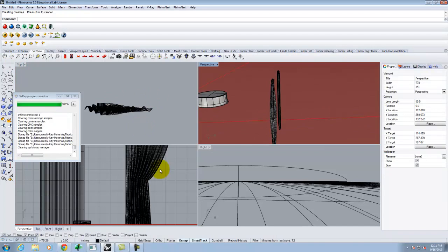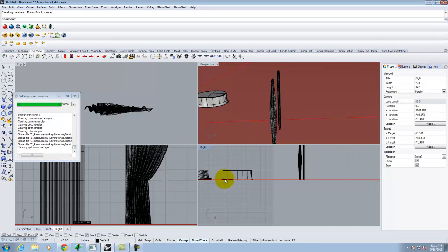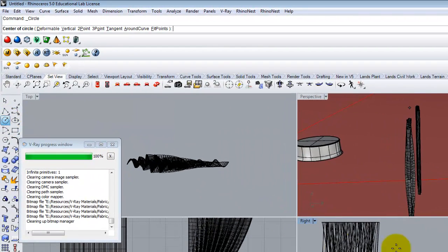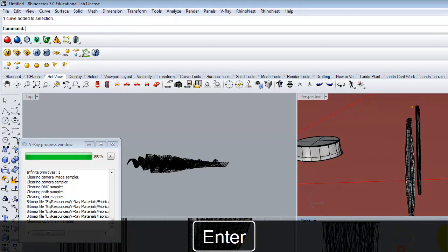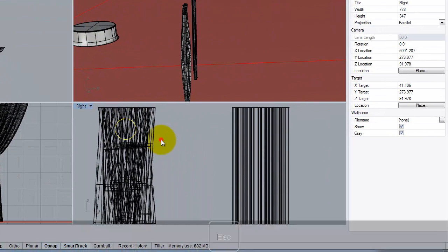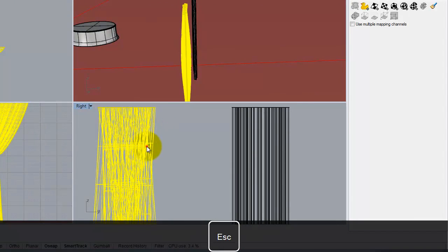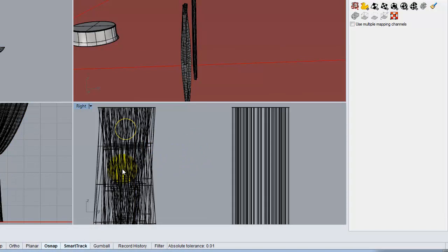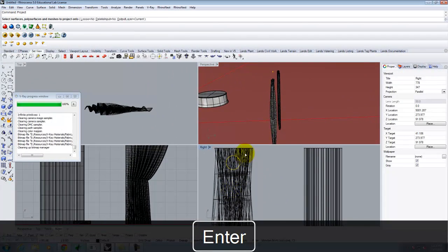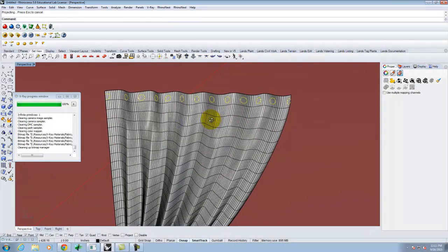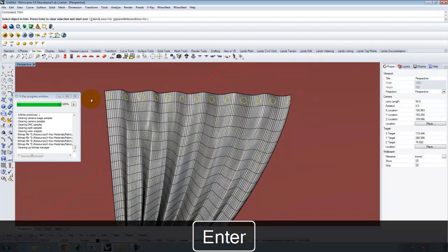Let's have fun. You guys are like, too much, stop talking, right? Okay, so let's say that I wanted a curtain rod to go through. So let's say I had a diameter of, I don't know, 1.5 inches. Something like that. Let's move this over to there. Like that. All right, let's take that curve. Project onto that surface. There's where the holes would go through. So let's trim.